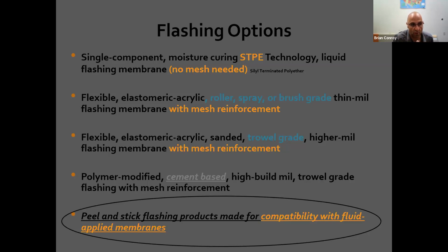That spray-on or roll-on material also can come in a trowel grade. Architecturally speaking, a lot of times I will find architects who really want that trowel grade specified and detailed out in openings and over joints and seams, and then they're okay with the roll-on over top of the rest of the surface. Again, a very good way to do that. You also have cement-based modifiers. We have at least one product that is an actual waterproofing base coat cement type of product that gets troweled on. They are out there for your use over things like stuccos and things like that.